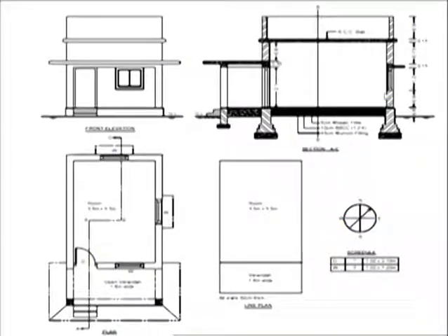Okay, that outer surface of the wall, the color is destroyed by this moisture, and sometimes this plaster is also deteriorated by this moisture. To prevent the moisture rise in this wall, this impervious barrier layer is laid on the top of the wall. That is called the DPC, damp proof course. That DPC may consist of synthetic filament, maybe bitumen. Sometimes they lay the concrete. They call it plinth level lintel. Sometimes the structural strength of the building is also increased because of this DPC.